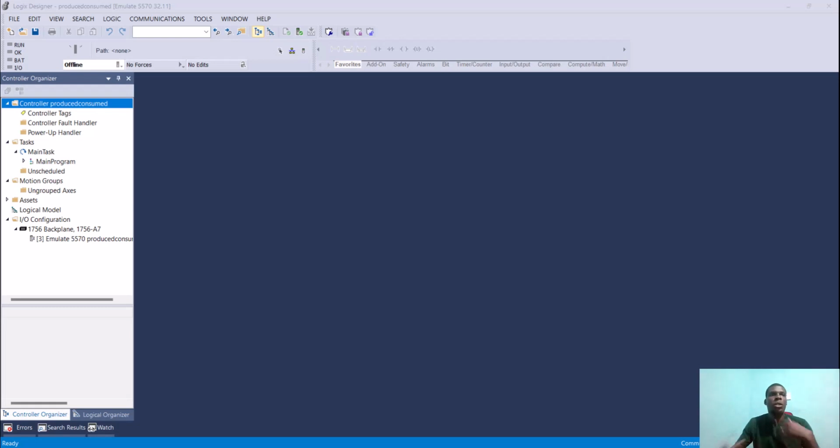So in this video we're going to be looking at PLC to PLC communication for Allen Bradley, and we'll be looking at produce and consume tags. Produce and consume tags is a way Allen Bradley can exchange data. Two Allen Bradley PLCs, CompactLogix or ControlLogix, can exchange data with each other for industrial communication.